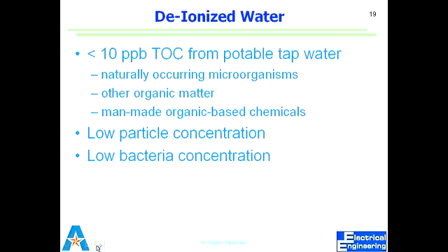Why 2,000 gallons per wafer? I mean, we're not going to use that much water in there, are we? We'll see how much you're going to do that. At the end of every cleaning process, there is something called a DI water rinse. DI water rinse is where you hold the wafer and put it in flowing water. You rinse it. The book says mostly a 5 minute rinse. So it means your tap is running for 5 minutes just for one wafer. In industry, of course, they have cassettes where you are flowing water to remove whatever is there.